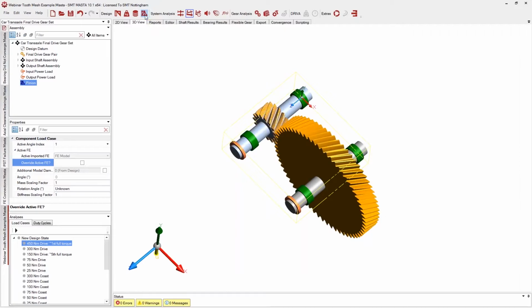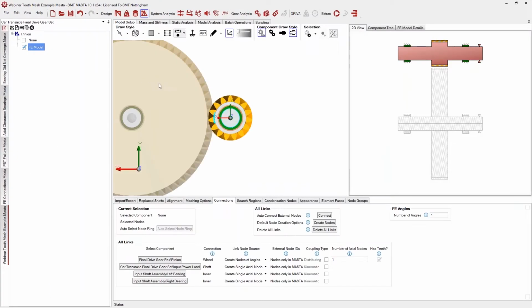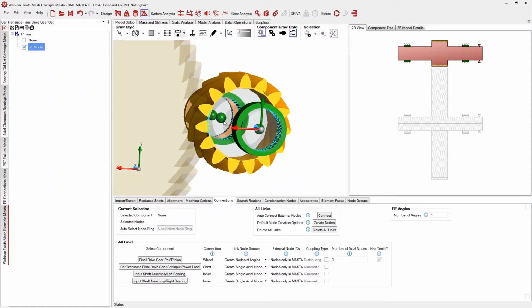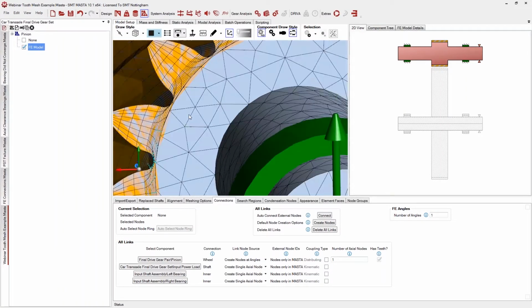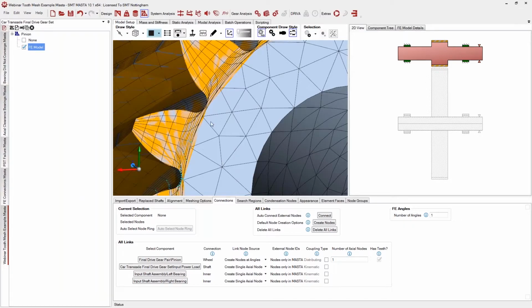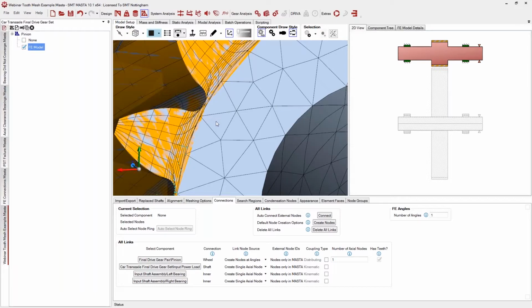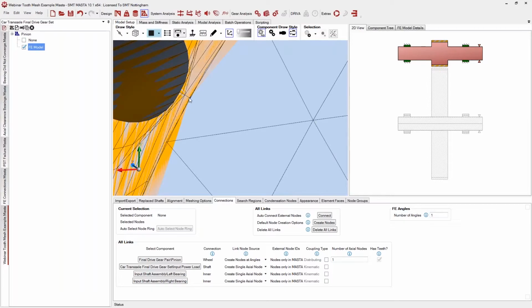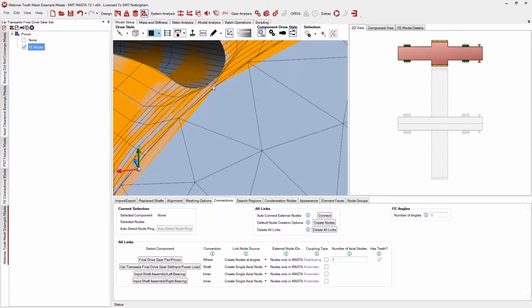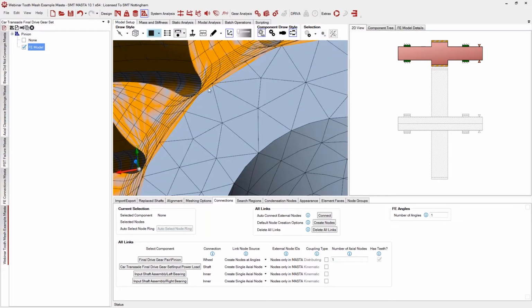Okay, so this means I need to go to the imported FE tab and have a look at my FE model. I'm not going to go hunting around too much in this model right now. Finding this without knowing where to go to could take a while, but the problem that we see is caused by this FE that's generated for the gear teeth not having enough space to extend because of the gear blank mesh. So you see that the gear blank mesh is very close to the root diameter, and this now doesn't give an opportunity for the tooth mesh to be formed and also to be stitched with an MPC connection to the gear blank.